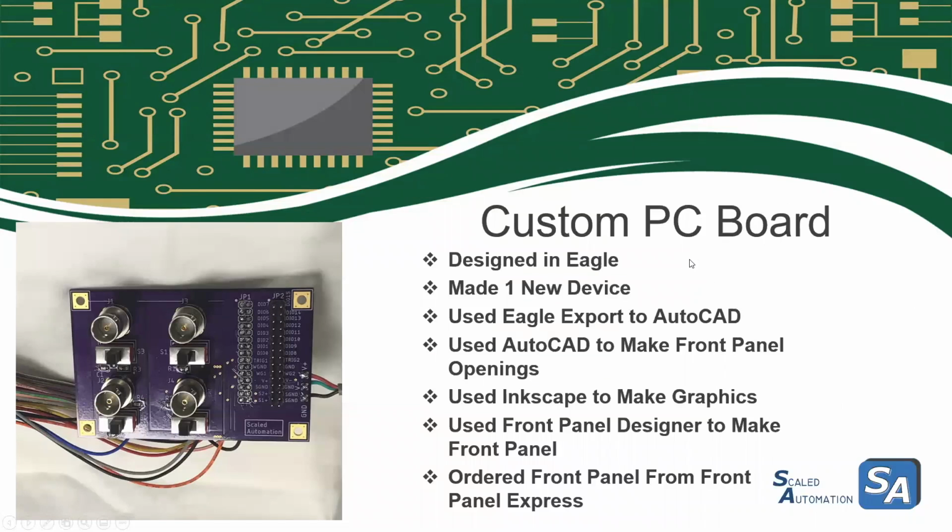So this custom board was designed in Eagle. I had to make one new device, and that actually was the BNC connector. The one I found in the library didn't match the spacing on it. And it wasn't hard. It was an easy one to design. And then the steps are kind of interesting because I used Eagle Export, an export out of Eagle, which will actually export a number of things, but one of them is an outline of the board and all its components. And it's very precise and exact, and it went into AutoCAD.